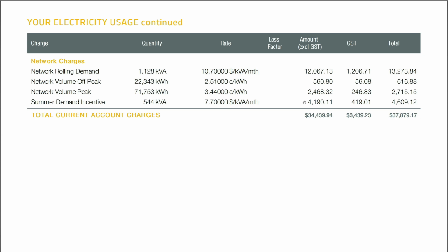All right. So I'm going to move off the invoice now, but I want you to understand here, the takeaway for this little discussion is that peak demand is a big dollar number in the electricity bill, much more than the consumption cost with this particular building, this particular retailer in this particular country. The first thing. The second thing is that when you have a peak event, they capture that high number and you pay the 12,000 for 12 months. Even though in winter, when our peak will be much lower because we're not running the chillers, you're still paying the 12,000 for the next 11 months because of that one mistake you made.